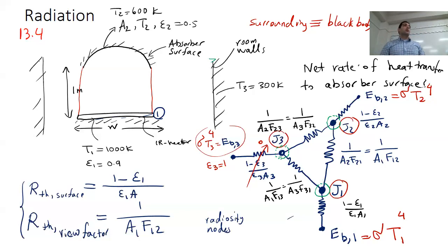This is what we assume. At every node, you are assuming that radiation or heat coming from the black body power comes to this node, to this radiosity, and leaves a portion this way, a portion from the other branch, which is typical, right? That's the energy balance. If energy comes in, a portion should go this way, another portion should go that way. Now later, and we're going to do this for all of it, we can find a negative number, which means that the direction was wrong.